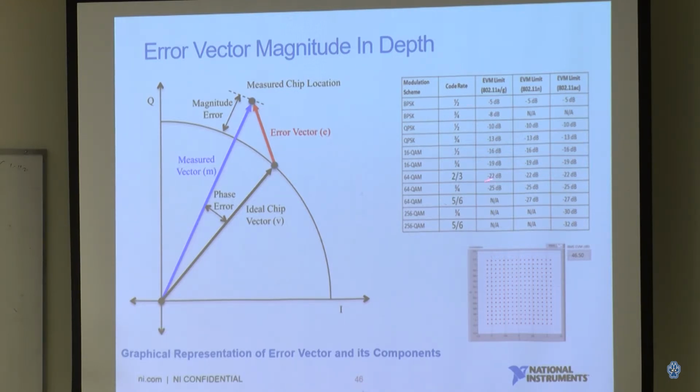And it's even more challenging when you try to develop your test equipment, because the IC design needs to be 10 dB better, but in order to measure 10 dB better, they need test equipment to measure their IC, right? So the test equipment needs to be 20 dB better. So let's say Apple has a cell phone trying to send a 64 QAM signal. They want to measure that their cell phone achieves 25 dB. They have to use an IC with 35 dB in spec. And the IC needs to be measured using test equipment at 45 dB.